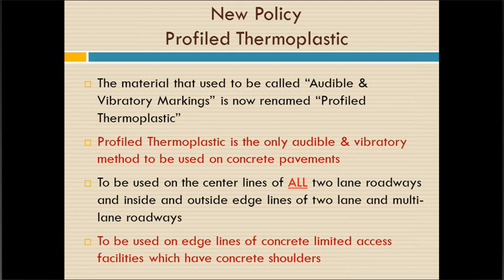So profile thermoplastic: we are only going to use profile thermoplastic as an audible vibratory method on concrete pavements. So if you've got a project out there that's an asphalt pavement that you've been using audible vibratory, you're going to need to change it to rumble striping.